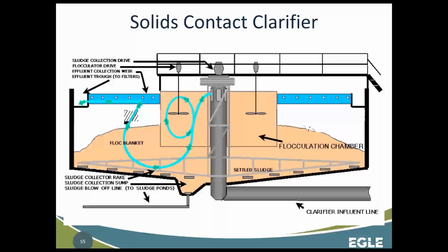Again, one of the issues with these, they're great. They're a lot smaller footprint. Problem is they are a little bit susceptible to thermal changes, which can lift the sludge blanket, causing the floc to carry over.